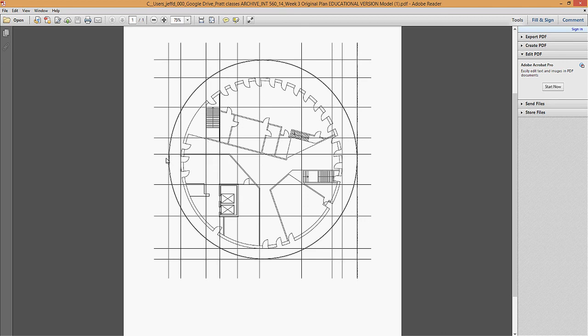When we rotate our document in Acrobat, because you don't want to make an extra effort in making the viewer have to cock their head in viewing your PDF file, you can rotate the document in Adobe Acrobat to be oriented horizontally. When you open your PDF file, Adobe Acrobat will open. This is Reader. I don't have Acrobat on my computer, but under Document, in the main menu, there's an option to rotate the pages. If you open that, there's a setting to rotate your document. Note when you do this, the default is to rotate the first page, and when we plot multiple pages as PDF files and combine them, make sure that you rotate all, not just the first sheet.